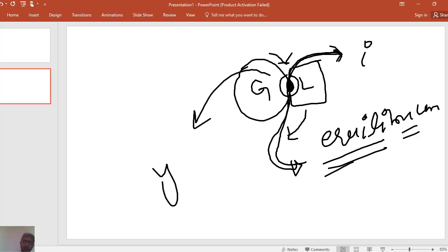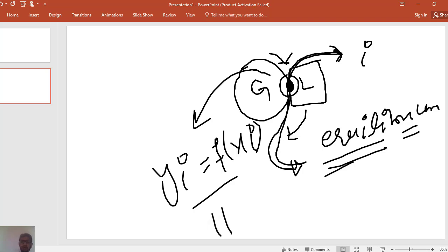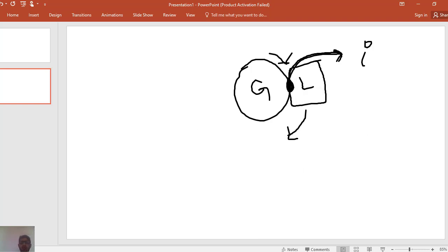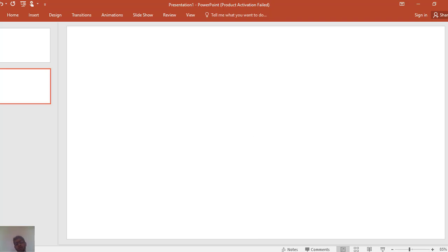In the gas, the mole fraction is y, and in the liquid, the mole fraction is xi, suppose, and it will be a function like this, or some equilibrium function like Henry's law type will be obtained. So equilibrium will exist at the gas liquid interface when the liquid element comes to the surface of the gas bubble.